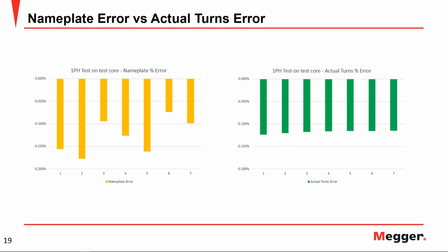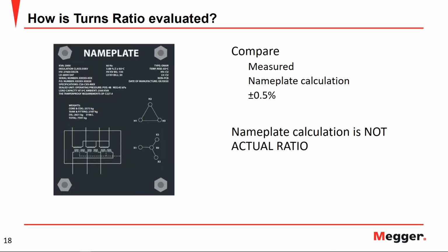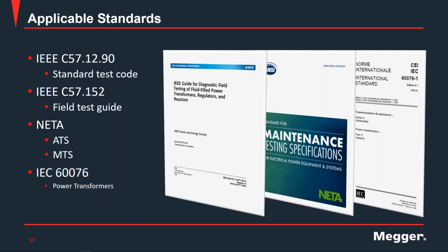You don't want to exceed the rated voltage when you're performing the excitation test, and you want to apply as high a voltage as possible, not to exceed the rated line to neutral voltage. That's the only criterion I would be mindful of. But as I said, the excitation test is a voltage dependent test. So if you did the test at 10 kV today, make sure that your subsequent tests are also performed at the same voltage level for trending and analysis purposes. Do not use different voltages, as that would impact your trending capability.